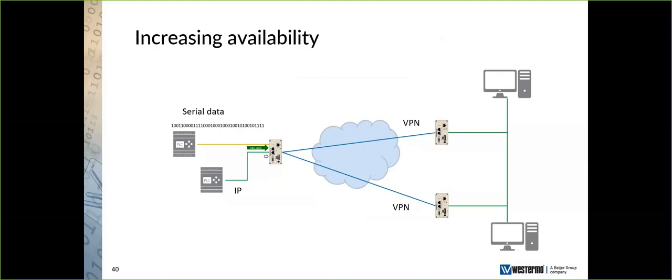Another thing that you can use is an APN, which is an access point name, which is private connectivity over a cellular network. That's being used a lot in utilities. What you should remember there is, according to the cybersecurity standards, IEC 62443, you should still use a VPN even over those APN services, because essentially you don't own that particular asset. So you should still use a VPN.